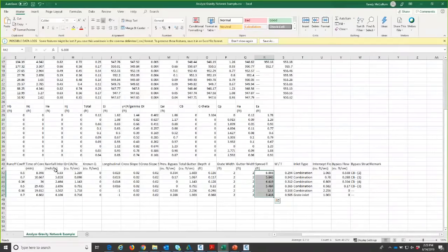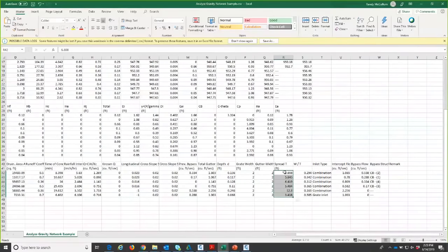But you could also just take the gutter spread equation, since this is a spreadsheet, and I could use the factors that are in here because all the information is already presented to me and recalculate gutter spread. I've submitted this observation to Autodesk, so we will see when they make the change. But until now, it is at least worth mentioning that the gutter spread right now, if you want to be very exact, you may want to recalculate it.